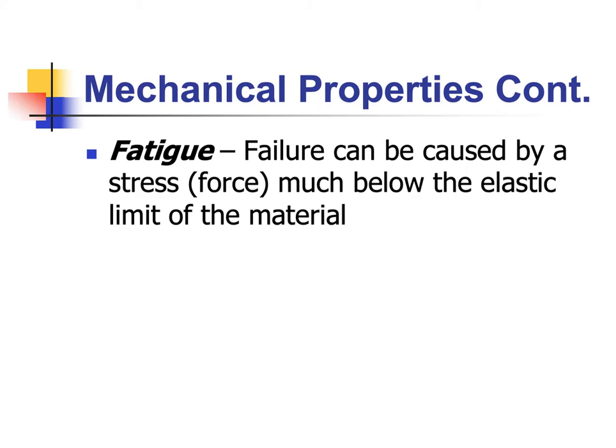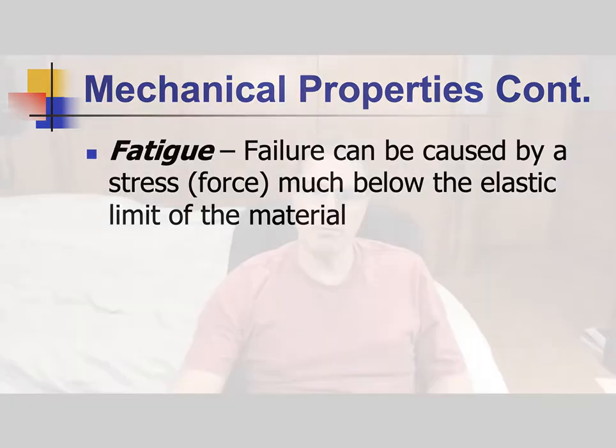Okay, fatigue. Hopefully you're not feeling too much fatigue right now listening to this, but fatigue is a failure caused by alternating stress. Something that happens over and over and over again. So metals can fail if you just bend them back and forth and back and forth. I don't know if you've ever done this with a paper clip, but if you take a paper clip and you bend it back and forth enough times, see if I can find one.